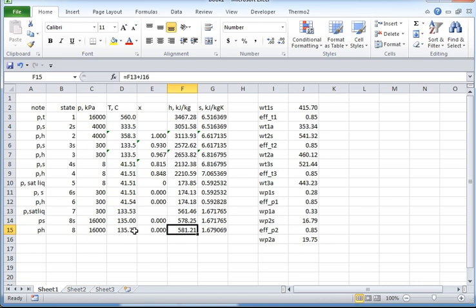So you can see that it's now 135.7 degrees C coming out of the pump. It came in at 133 into the pump. So there was some increase in temperature of the pump. It was a huge pressure increase. But where is state 9?